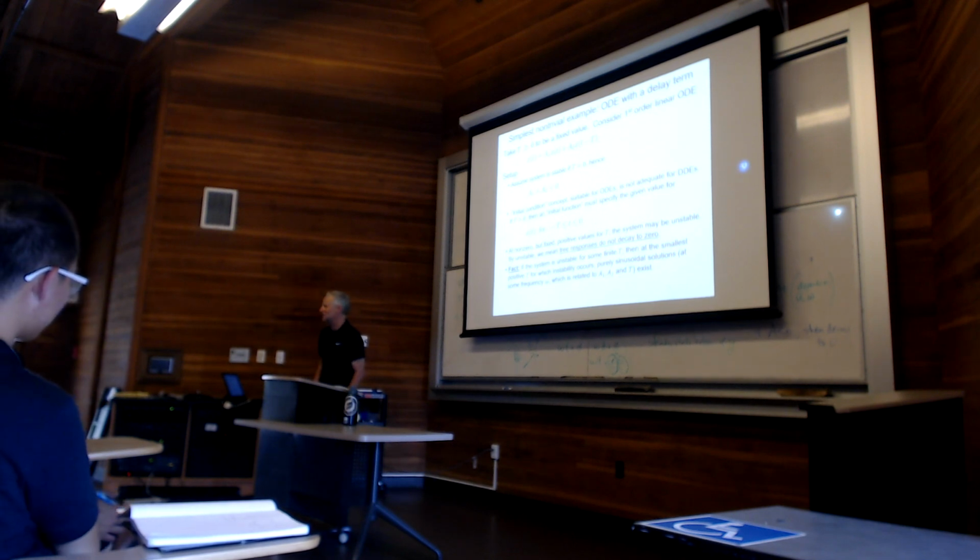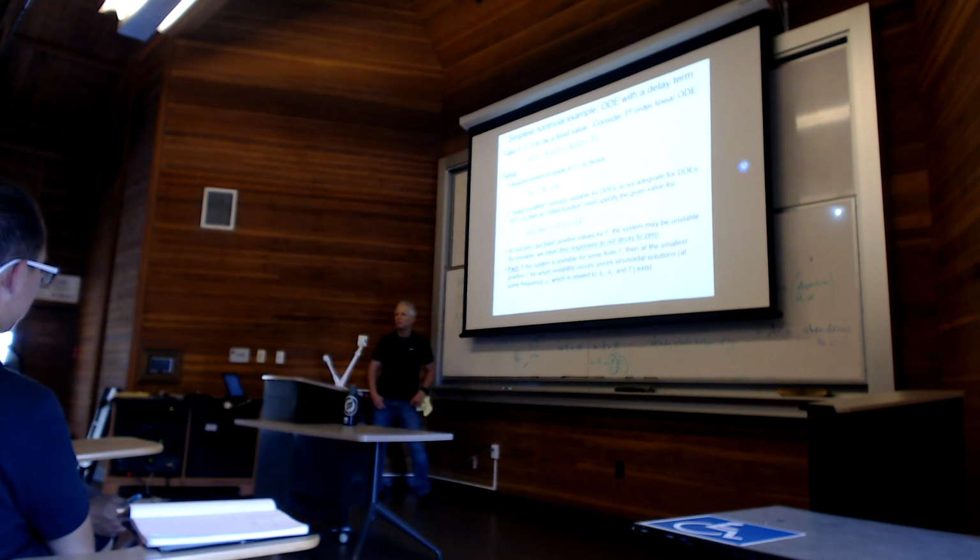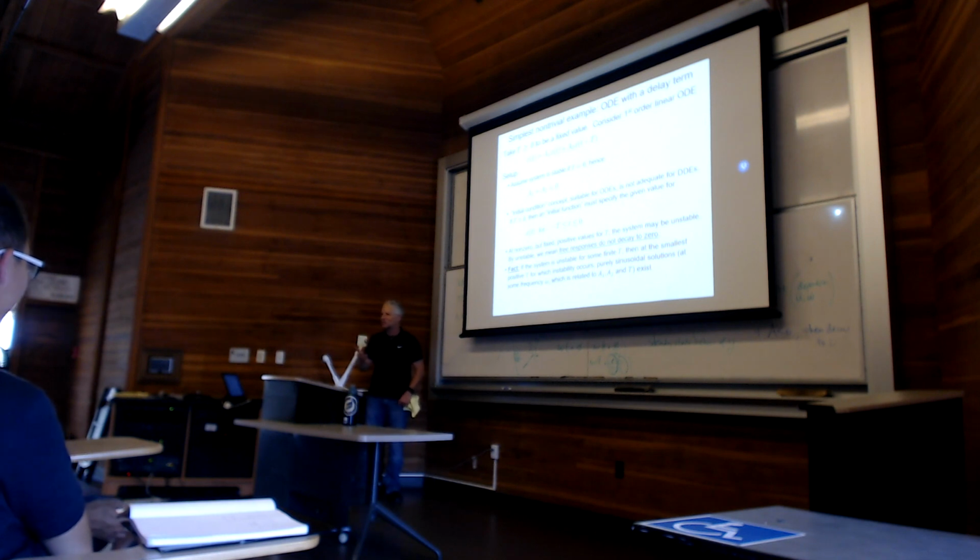And think exactly how this is going to work. You get in and take a shower, and it's fine. I'd like it a little warmer, just a speck warmer. So you turn it, and you wait your 1 second, and nothing happened, because there's a long delay here, right? And you weren't counting on that. So, oh, okay, a little crusty, or someone took a long shower before me and I've lost the hot water. So I turn it a little more, still nothing happens. I turn it a little more, still nothing happens. Finally, it's like, perfect, now it's coming. But then it starts getting too hot, because you've already turned it 6 times as far as you should have. So then you start turning it back, but what happens, it gets hotter.